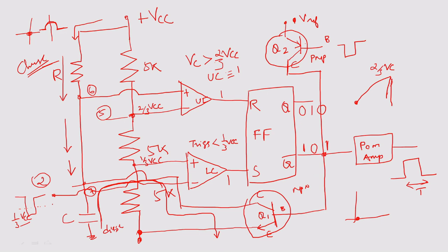You know this is giving 1 from the logic of Q bar, so the transistor is on. This is clamping the external timer capacitor circuit to the ground, so it is discharging. This is your stable state. Here the discharging has fully happened. When you apply the trigger pulse, you get the higher state. Then again it is discharging and going to the stable state, right? So this is how it works.